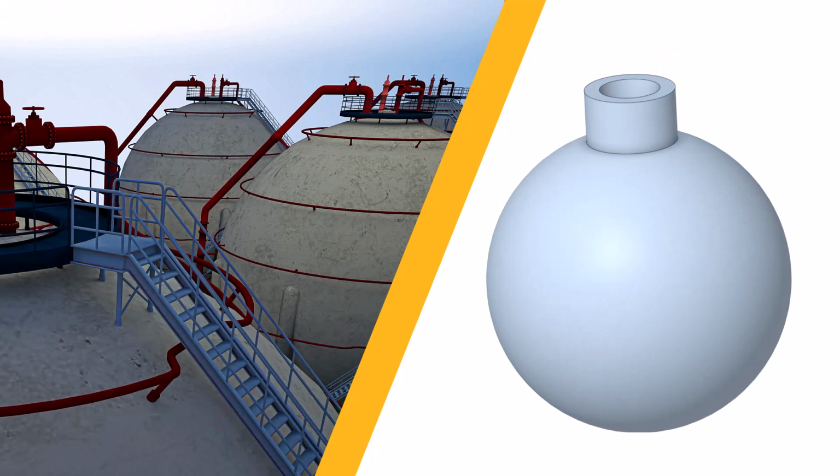Note that the pressure vessel is connected to additional piping, which has been truncated in this model. Although we may usually define boundary conditions to represent the effect of the truncated portion of the geometry, we're allowing the truncated end to deform freely in this demonstration. We also assume isothermal conditions without gravity or other loads applied on the model.